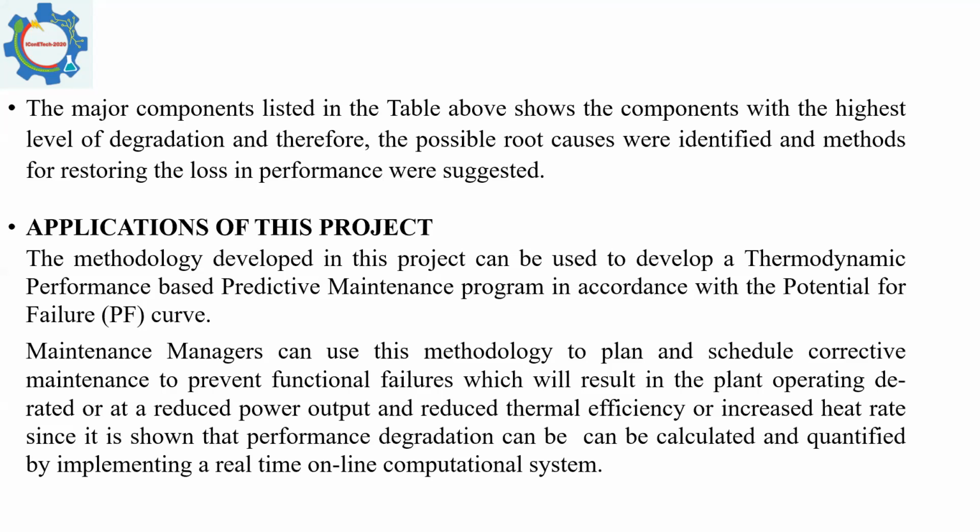And on the basis of that, we have to calculate all the component design performance parameters. We have to calculate all the component design on the basis of the first law and on the basis of the second law, because we're basically using both laws in tandem to show and predict degradation in performance. And then based on data we obtain from the plant, we were now able to calculate the actuals. So we can now compare them with the design parameters and look at that level, the level of degradation.